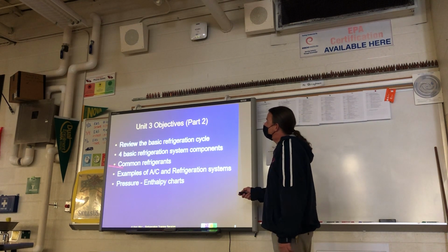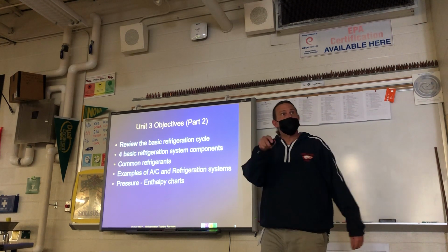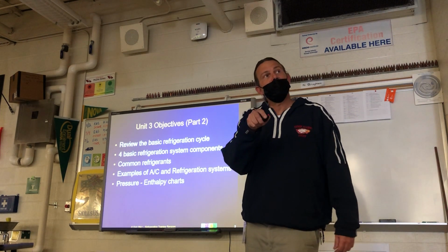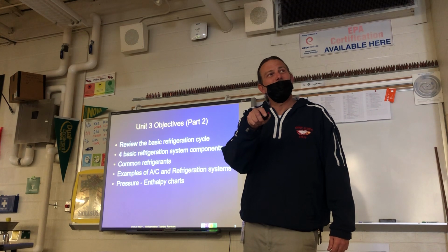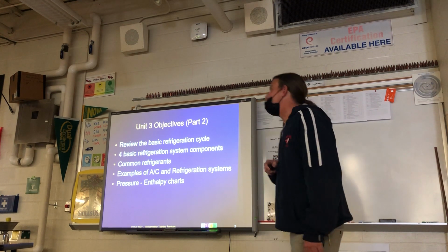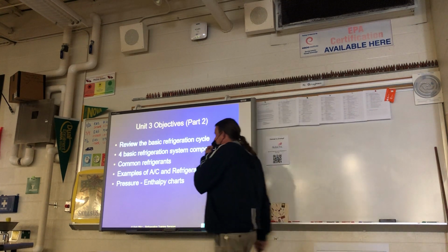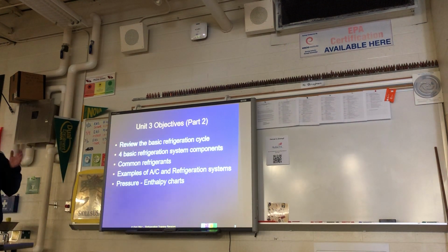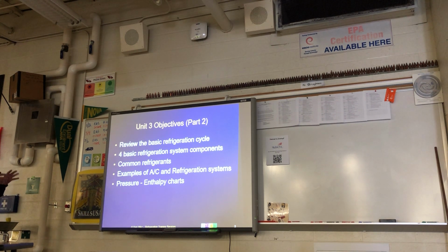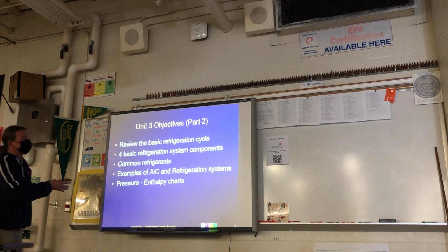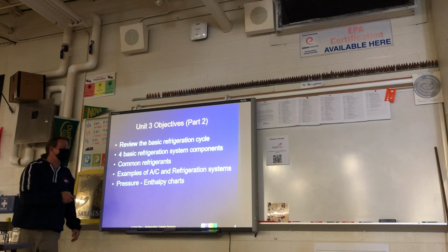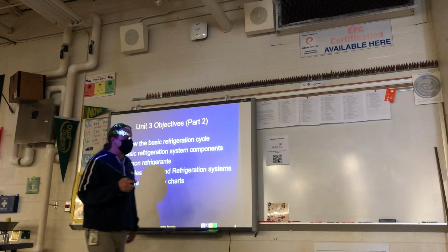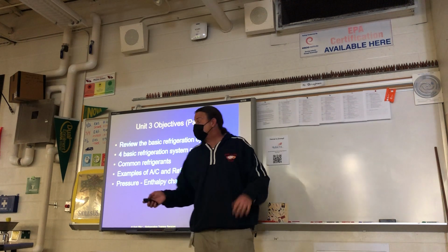I want to show you there's a thing that you can see over here. Once we break down the system and you start to diagram it, we can plot the refrigerant cycle on something called a pressure enthalpy chart, a PE chart, that is specific for each type of refrigerant that we have out there. On the engineering side, you can use it as a troubleshooting tool in the service side, but it's really more for the engineering side of HVAC systems, to calculate capacity and things like that.